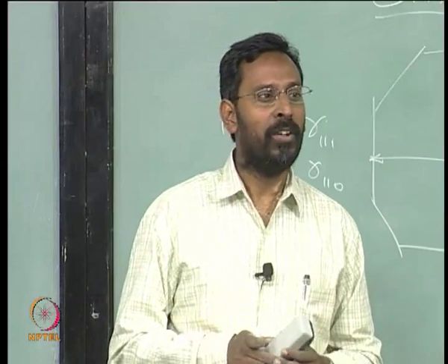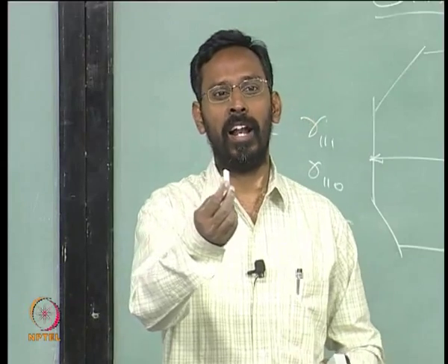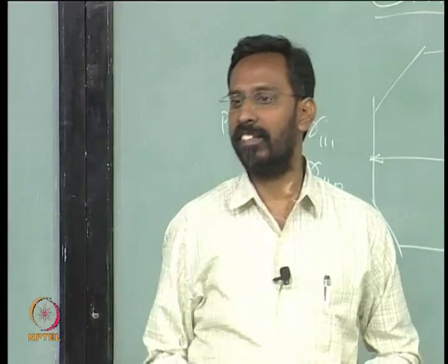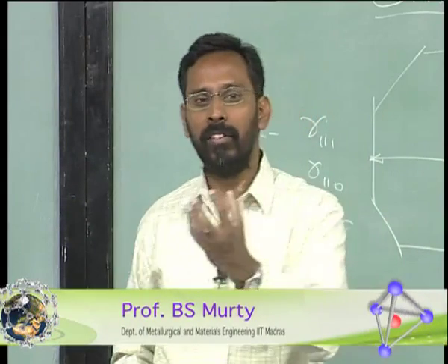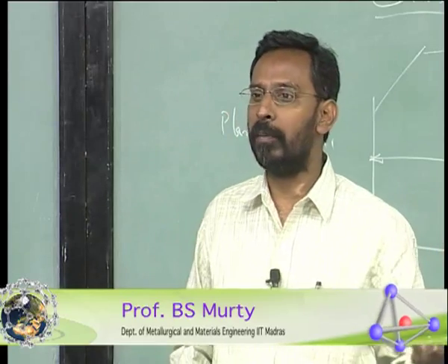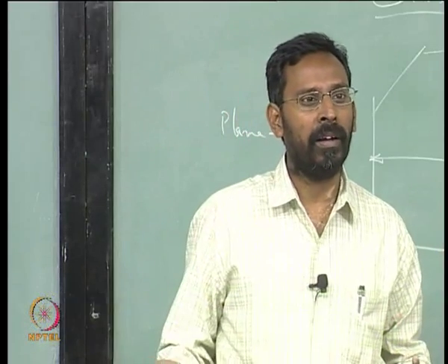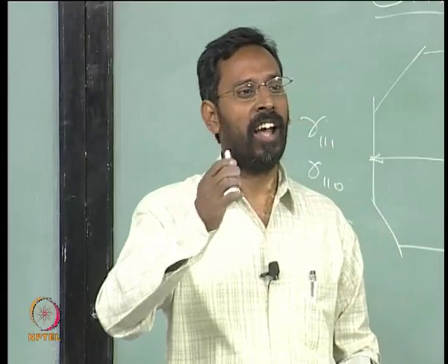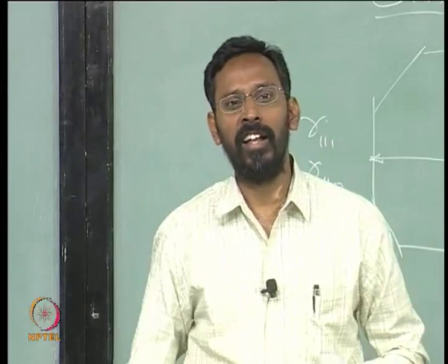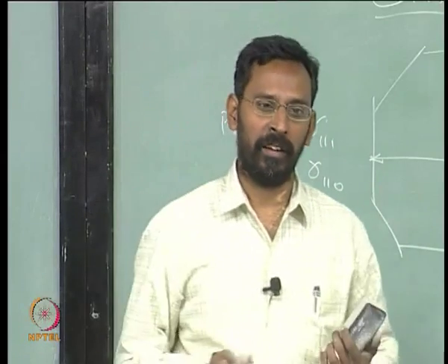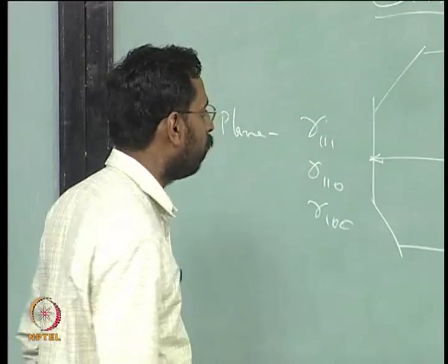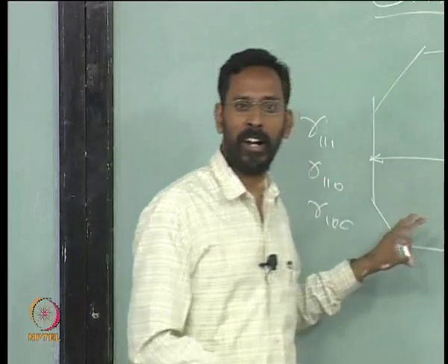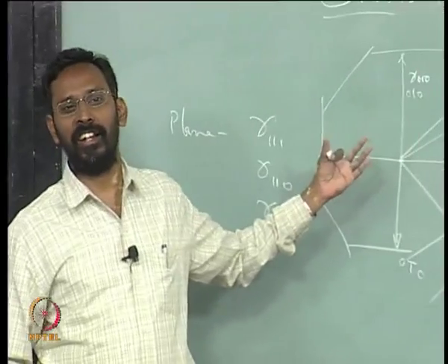That is the reason why you will always see, for example, in aluminum silicon alloy, silicon needles. In an iron carbon alloy, the cementite is like blocky, chunky particles. Why does this happen? Because certain directions have a faster growth rate; in silicon, it grows faster there. So, this is another issue that one needs to consider, but for the sake of academics one can calculate shapes like this.